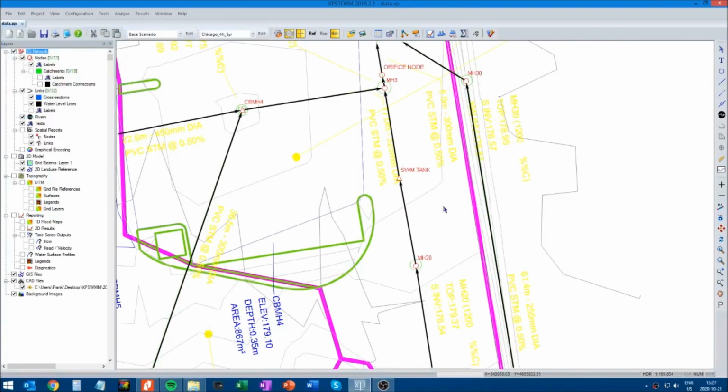Okay, so after putting in this stormwater management tank, XPSWMM keeps crashing on me. That's the problem with this program. Sometimes if it doesn't like something, it just keeps crashing, doesn't tell you what the problem is, and it takes a long time to debug. And there's not much you can do to figure out exactly what it is, so just keep trying something different.